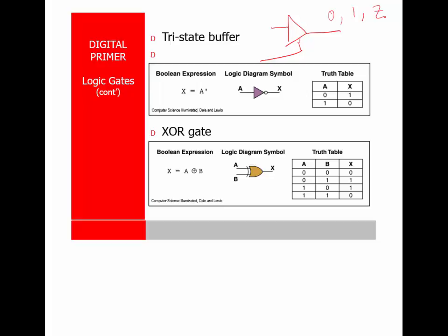They all change, and the output changes. But because the number of gates that the various signals go through are not equal, you get an erroneous output before you get the correct output. And that's called a glitch. And sometimes you'll put buffers in the circuits in order to prevent glitches.